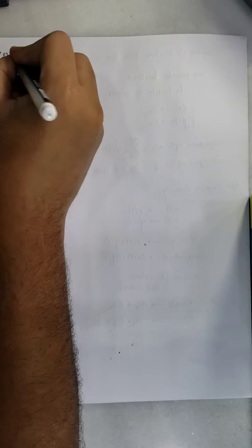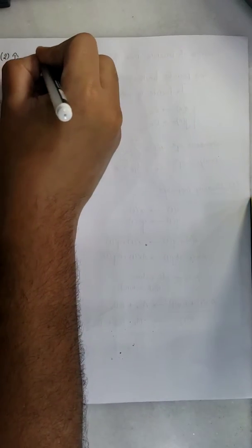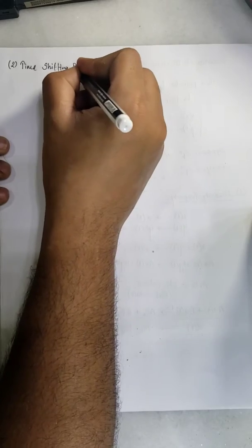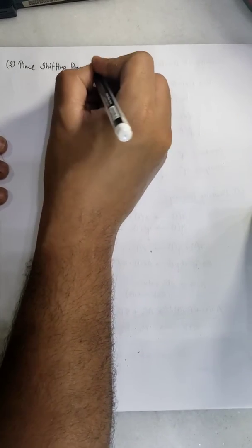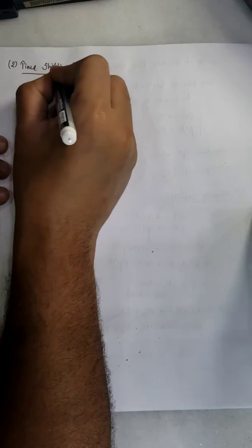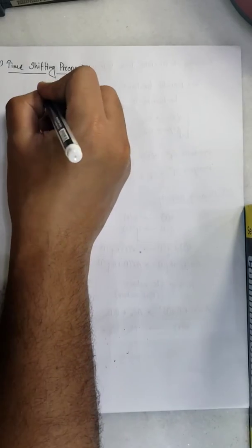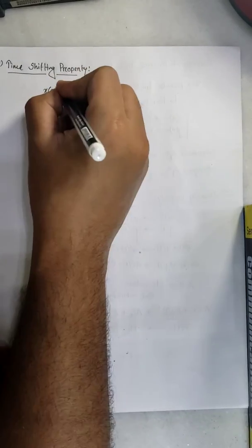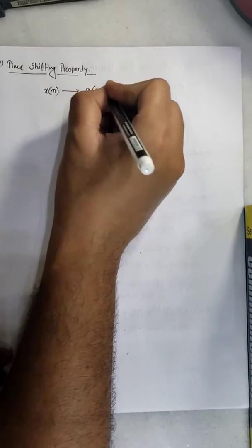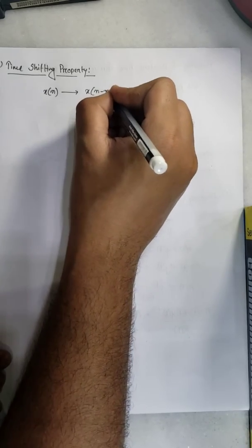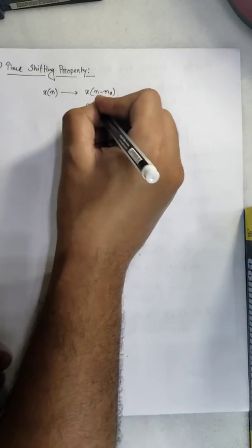Okay, now let us go to the next property, which is the time shifting property. Now this property says that if the periodic signal x of n is shifted to x of n minus n naught, that means the signal is delayed by a factor of n naught, or it may be advanced by a factor of n naught as well,